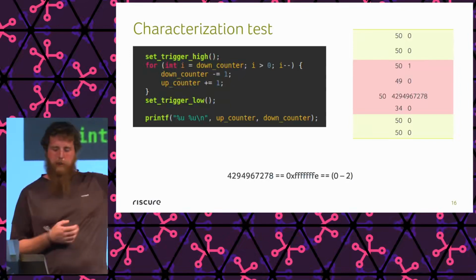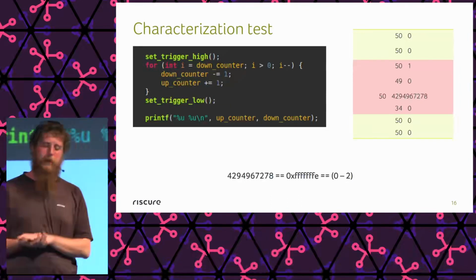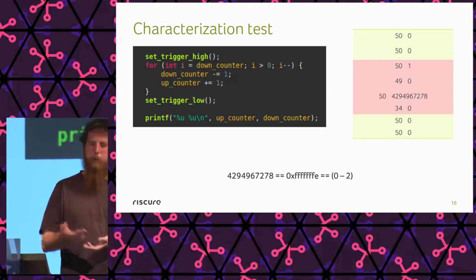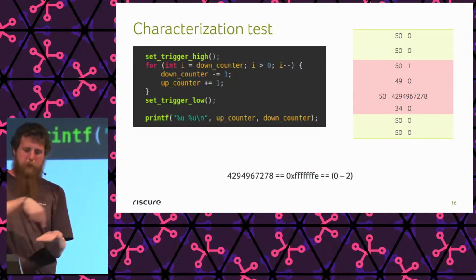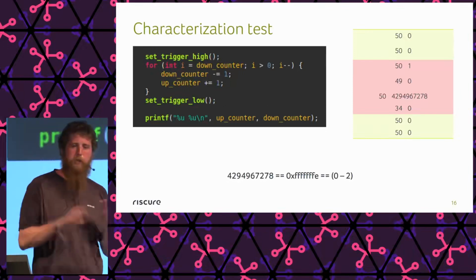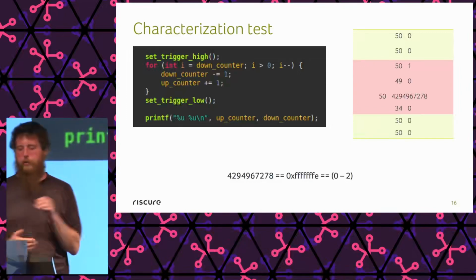We use very simple things like this as a first step, often to get an idea of how powerful your glitch needs to be and where in space above the chip it needs to be, with a very coarse-grained scan to reduce some of these parameter ranges that we're interested in.